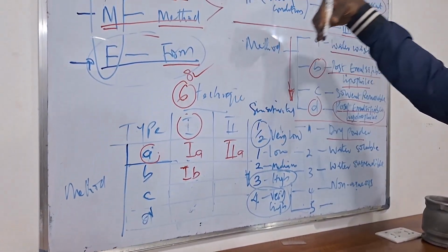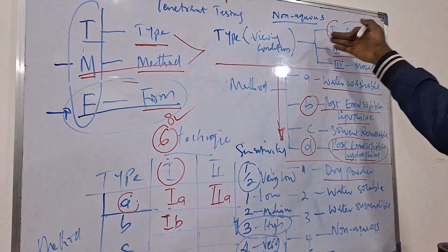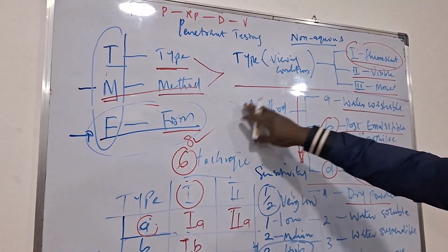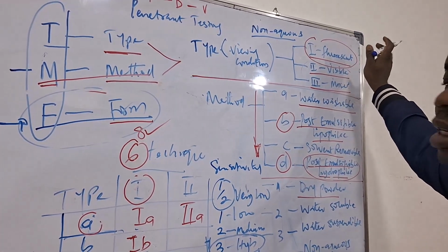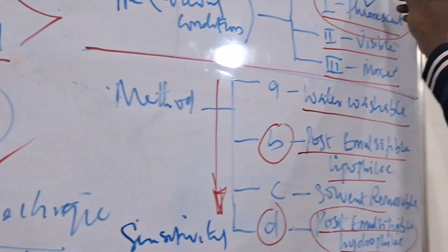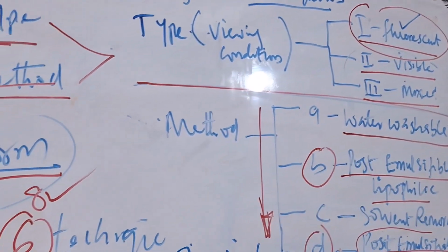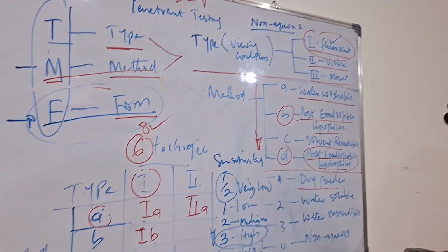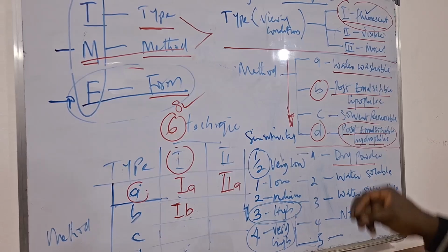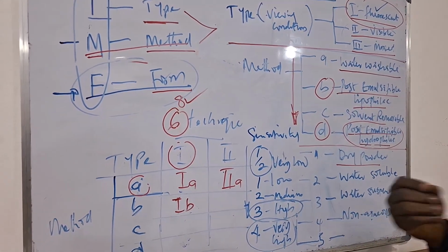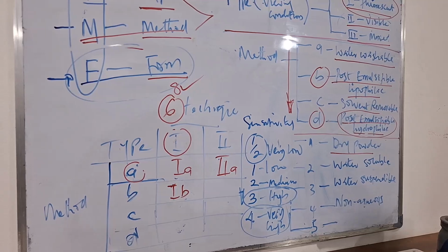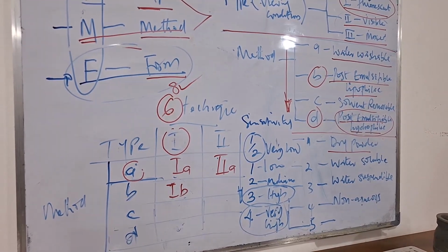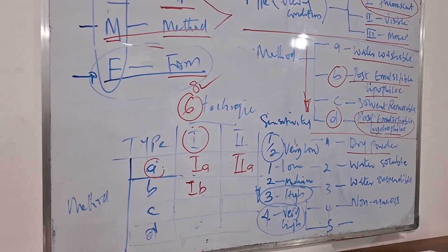We should also have it in mind that in aerospace inspection, you don't use visible penetrant at all. You're always using the fluorescent, because in penetrant testing for aerospace you require very, very high sensitivity, and in that class you require a sensitivity of 4, which is very high.